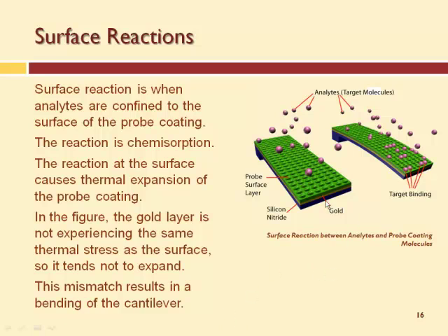So we've got silicon nitride and then gold on top of that, and then our probe coating. And then the analytes or the target molecules that we're looking for will only stick to this probe surface. That's the idea. Some of these cantilevers are designed so if the analytes stick to the surface, it causes the surface to either expand or contract, so the cantilever will bend.